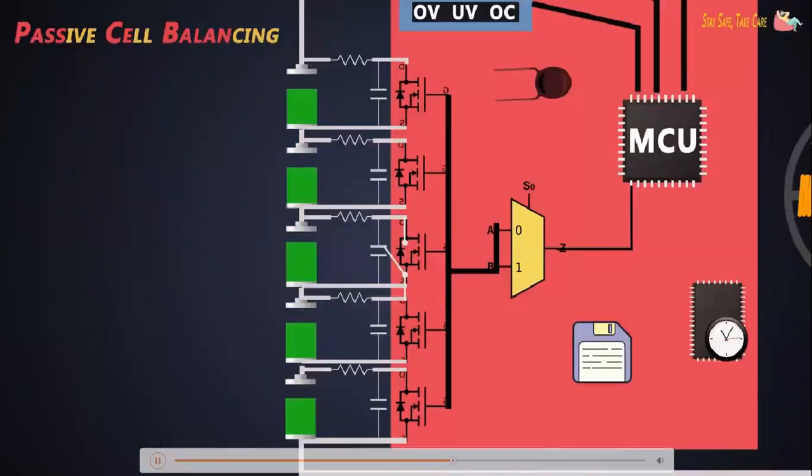This process minimizes the charging rate of the weaker cell. Whenever charge goes in, the weak cell tends to go near to its full capacity, so the MOSFET is turned on. So all the cells along with the weaker cell charge at the same time.